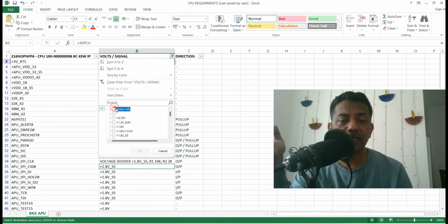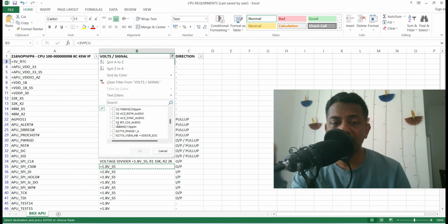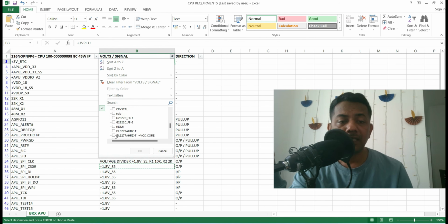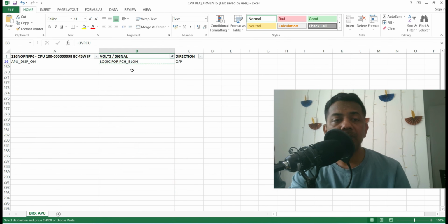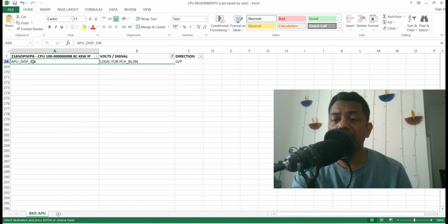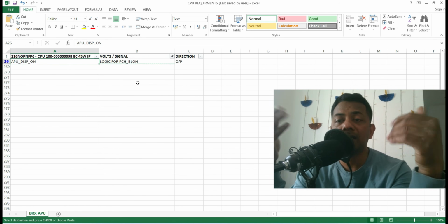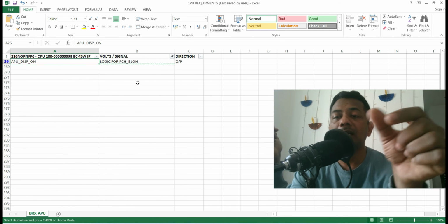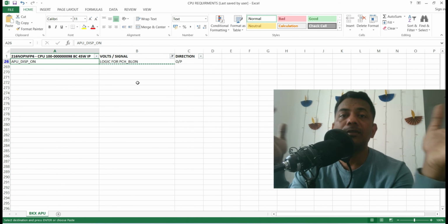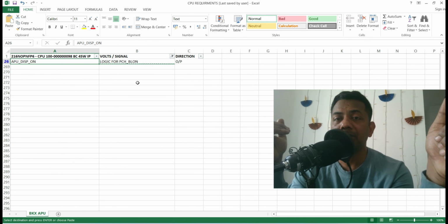Next, if I take the signal level, these all will come, the crystal, HD, ACL, those things will come. And one minute, I'll tell you one more thing, some logic or whatever it may be, display related, EDP related. You won't get backlight LED or display. You can get the display on HDMI but not EDP. That also means the EDP section has a problem or issue.